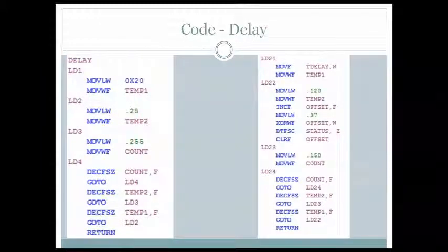Shown is the code for our 2 delay routines, one of which is static and the other being dynamic and based on the current value of T-delay. This code exploits the length of the PIC16F84A's clock cycle by performing a large decrementation within 3 loops, causing a delay as the system works to perform the computation.